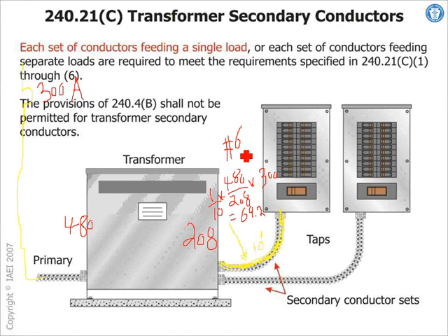How much current can number 6 carry, guys, under the 75-degree column? 70. Then this circuit breaker cannot be more than what? 70 amps. That's the smallest wire, and the largest overcurrent protection device that can land the number 6 on it. That's your 10-foot rule for a transformer.